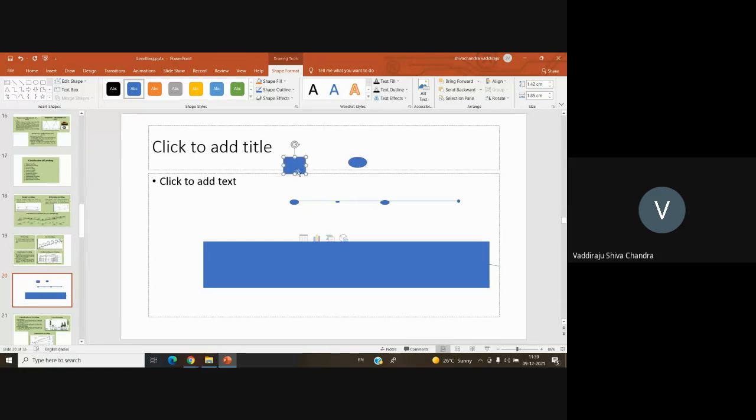Okay, so this is going to be my backside. This is my instrument position. After I take that backside, then I'll be placing my staff at each of these 10-meter intervals. I'll be placing my staff here and taking the reading. I'll be placing my staff here and taking the reading. So at every 10-meter or 20-meter interval, I'll be taking the staff readings only along the center line of the stretch. So this bottom rectangle is the width of the road which I want to lay. So I'll identify where the center line is, and along the center line, I'll be taking the staff readings.